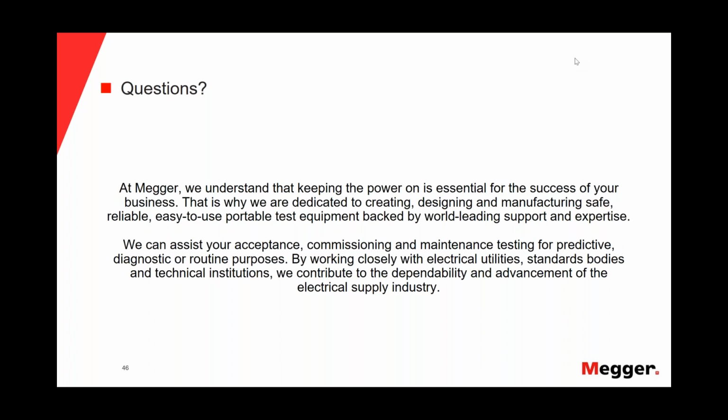I will say that under normal conditions, we will spend between 10 and 15 minutes per phase, okay? I will say that maybe 45 minutes will be the complete time we will need for a partial discharge test in the 3 phases, at the maximum. Of course, if you have some issues with the background noise level, or if you have a poor concentric, etc., maybe you can take a longer time. But I will say that between 30 and 45 minutes will be the time to do a PD test in the 3 phases.